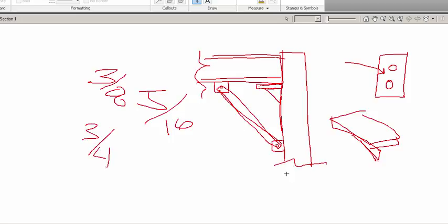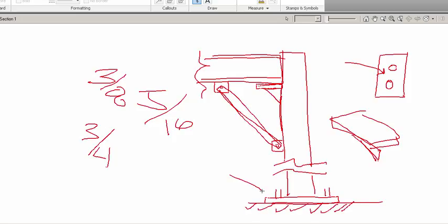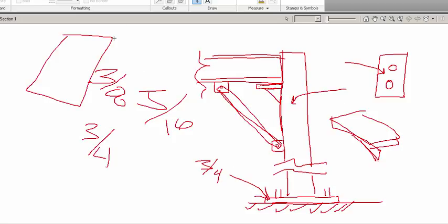One in particular is the base plate, which is a plate that is actually welded to the bottom of a column, where bolts are put in so that it can be anchored down to the concrete down below. This oftentimes, according to a variety of standards, will be 3/4 inches, depending on how large these columns are and how much stress is going to be put on it. So they'll actually just take 3/4 inch plate, cut it out to a certain size, drill some holes in it, or plasma cut it if they can, weld the column to it, and take it to the field for install.